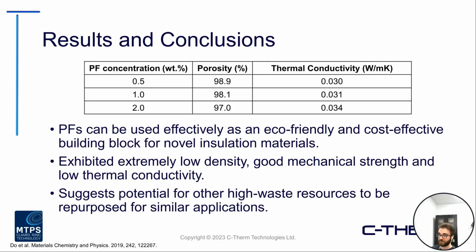But just diving right into the thermal conductivity results and some of the conclusions that they drew from the study. They noted that increasing pineapple fiber concentration by weight had a link to the porosity that was generated within the structure. So more fiber resulted in lower porosity. And that ended up affecting, of course, the thermal conductivity: the lower the porosity, the higher the K went. So actually having a lower amount of fiber, having higher porosity, did result in the lowest thermal conductivity, or you can view that as the best insulating material of the series that were tested.